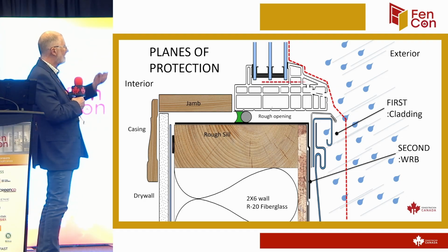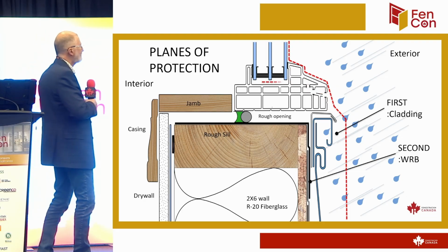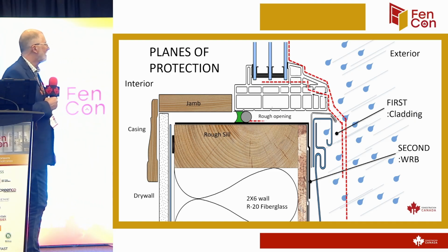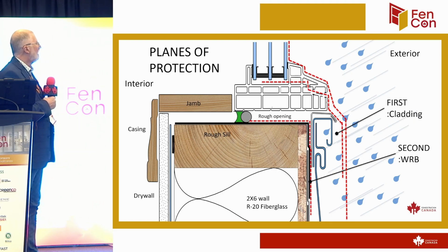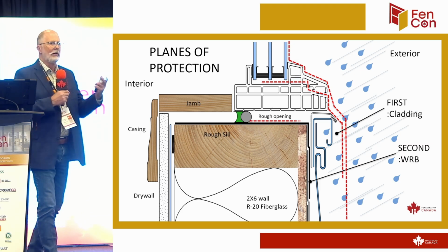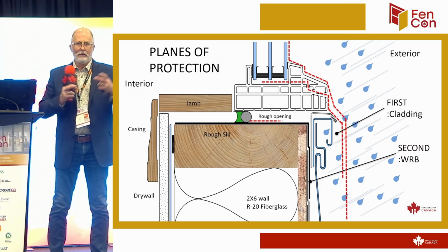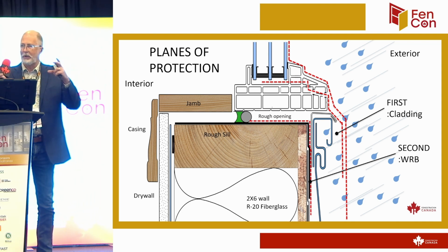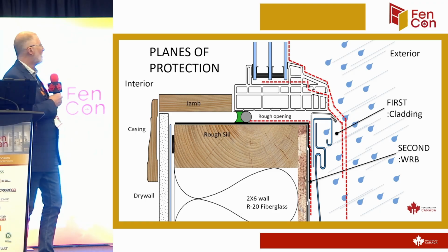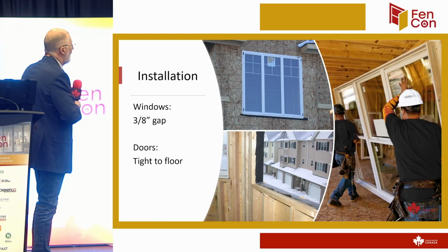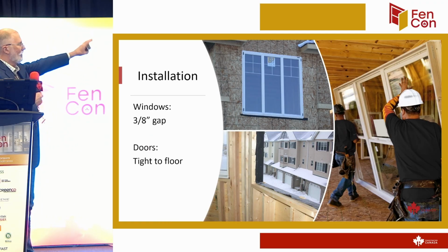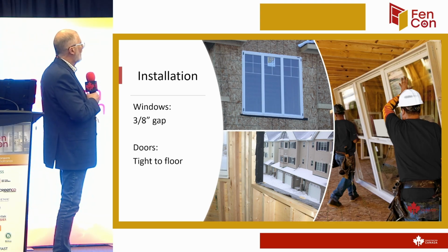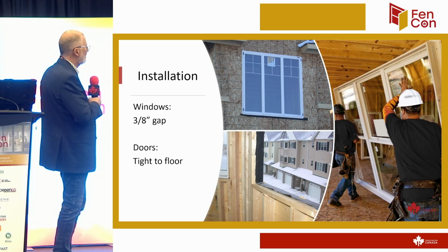And you still have that internal drainage that you had with the flange window. And then you also have the ability to get rid of water that gets into the rough opening. So those are the basic principles. And every window is slightly different. Some are more finely tuned to have more cavities, more spaces. Spaces are smaller if you want to spend more money on them. Some of them are insulated. But when it comes back to this question about the 3/8 gap in installation, what do you see wrong with those two middle pictures?